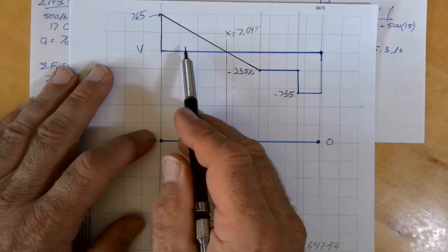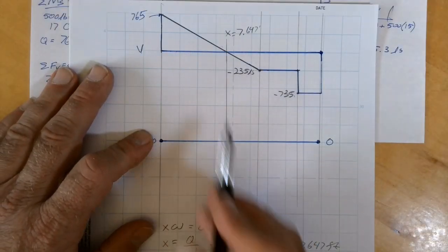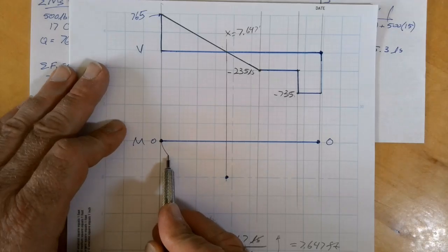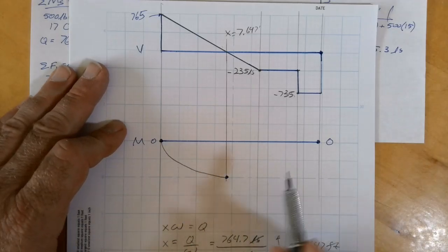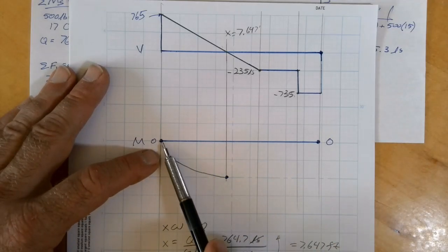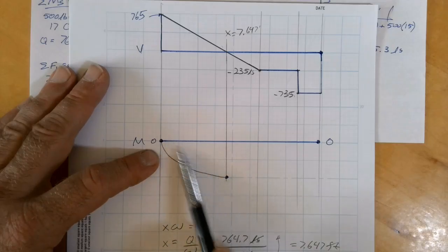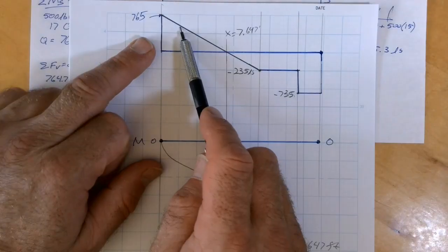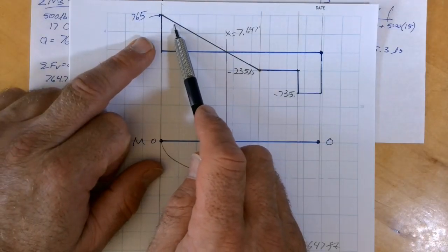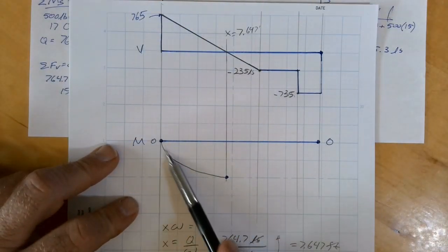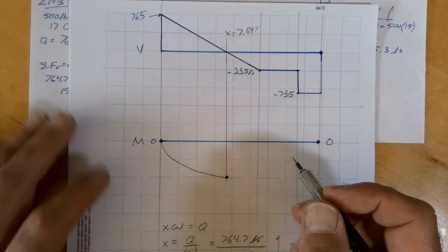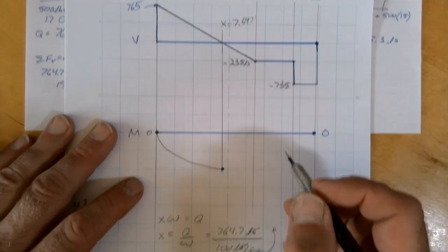So the shape of the moment curve from here to here, because this is triangular, this is parabolic. So I'm just going to draw it in. You might ask, how do I know if I draw a line like that or a line like this? You can look at the magnitude of the shape. So here, because there's more shear, the rate of change of this line is going to be greater. So it's going to get bigger faster because this is big early. That's kind of conceptually how I think about it.